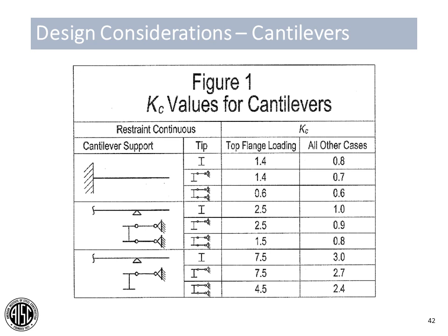You will initially determine the cantilever support condition, whether you have a fixed cantilever or a propped cantilever, and then what your support flange bracing conditions are, whether both top and bottom flanges are braced or just the top flange only. And then you'll look at the tip condition of your cantilever itself, whether it's free, top flange braced, or top and bottom flange braced. And then the loading application location, if you're on the top flange or any other case. And then you've got your K sub C values that are tabularized for you.